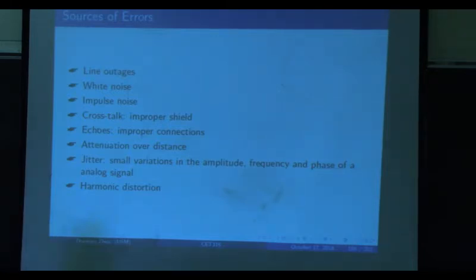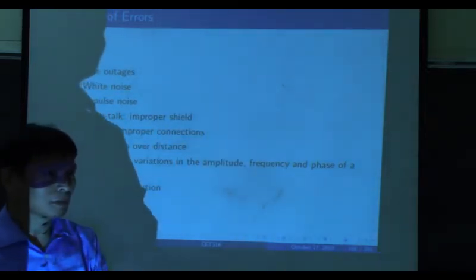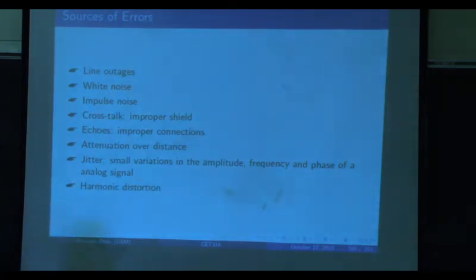Again, when you design the amplifier, you say this is a linear amplifier. In an amplifier, you always use transistors. Why do you still call it a linear amplifier? Because the output equals a constant times the input. It's linear. Why? There's a condition for that. That condition is called the small signal approximation. Only when the input is small, the output is approximately linear to the input.